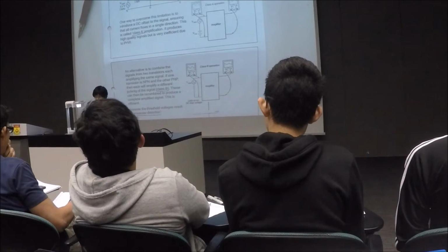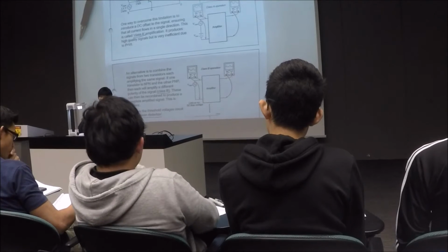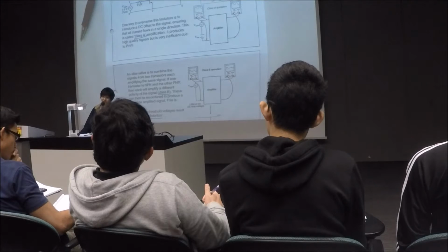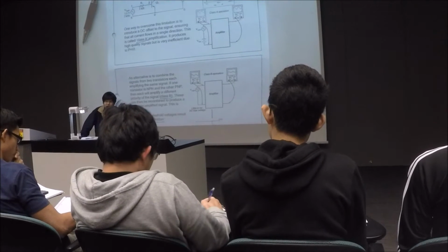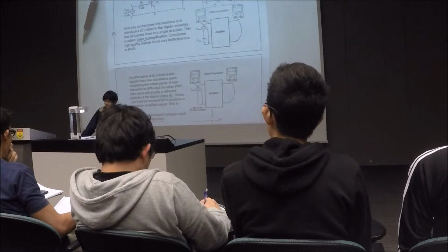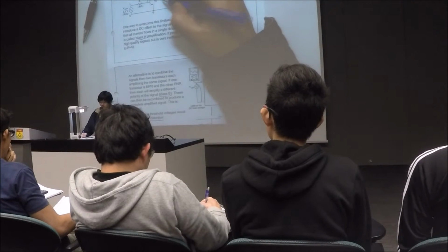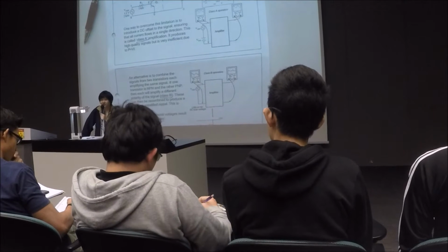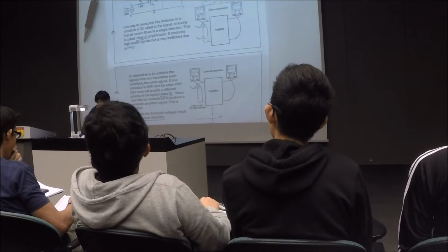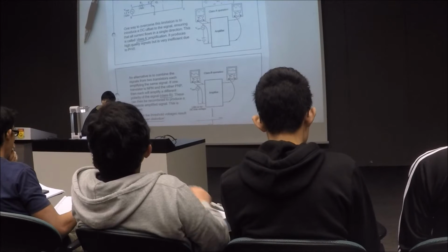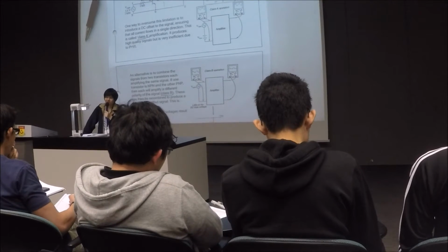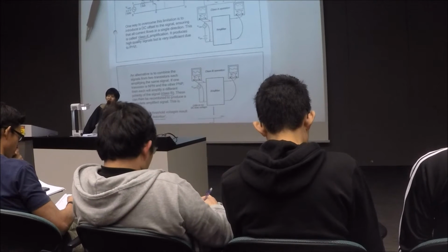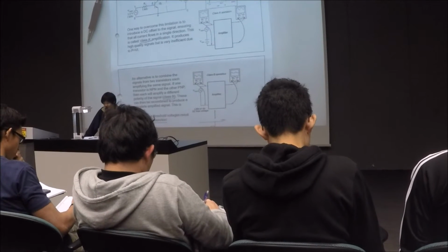So in this way, we call it a half rectifier: you have a full sinusoidal wave input, while in the output, voltage across C and D, you will have a half wave, so we call this a half wave rectifier. The problem with this half wave rectifier is that it is not power efficient, because you can imagine it cuts off half of the waveform.